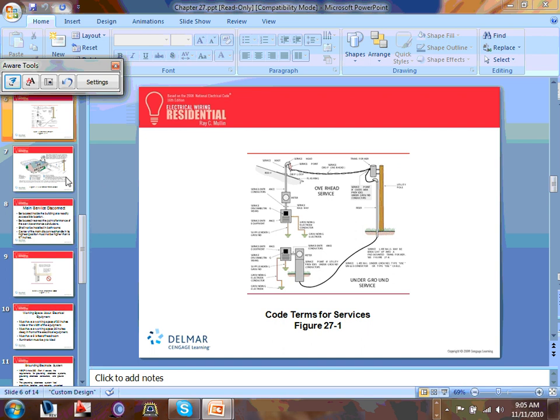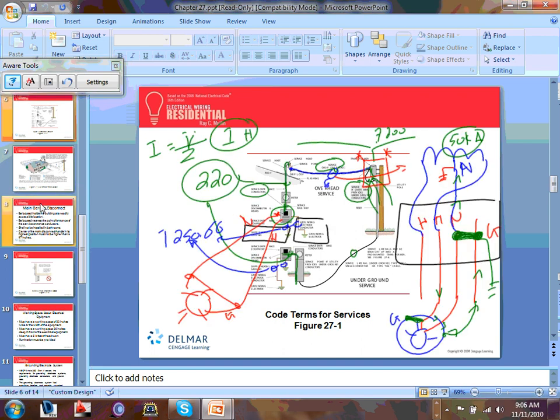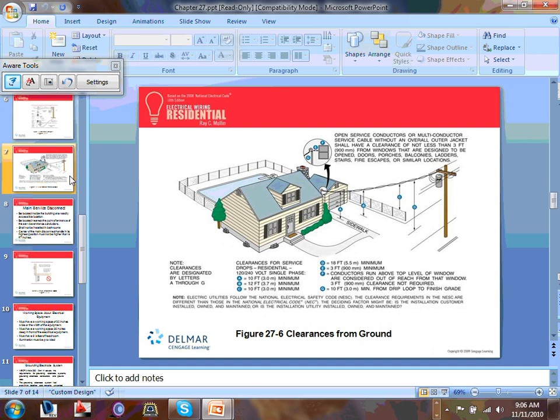Hey, I got a question. How do we determine whether a duplex is considered one service entrance, even though it's just split right at the meter? Very good point. This service drop is a service. From here, this is one service, guys. From here, I can split this one into as many as I can because it's one service. Except for the first disconnect, if you have 6 or more, you have to provide a main. In our situation, we have 4 or 5, so we don't have to have a main. What we're talking about is bringing another service from right here to the same building. A whole complete another service.